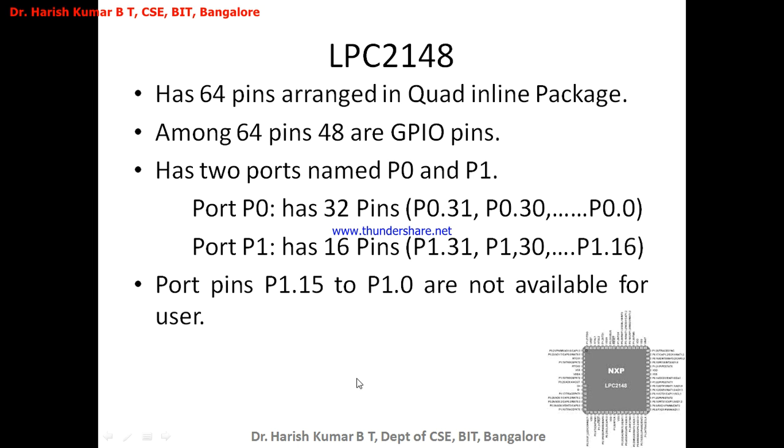Now with this you understood that LPC2148 in general has 64 pins, arranged in a quad inline package like this. Among the 64 pins, 48 pins can be used by the user as general purpose input and output pins. And again these 48 pins are grouped into two ports, port 0 and port 1.